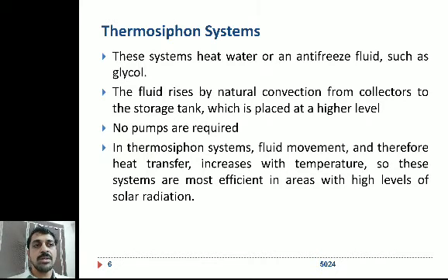So fluid movement and therefore the heat transfer increases with the temperature. So these systems are most efficient in areas with high levels of solar radiation. So wherever higher levels of solar radiation is available, these thermosiphon systems are mostly effective, and it will convert thermal component of solar radiation into hot water efficiently. I will show you the diagram.